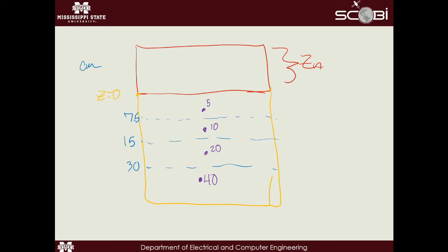And at the very bottom, one of the inputs into the program is something called ZB or ZBottom. And what that does is whatever your input is, you're going to add that to your last soil moisture probe location. So for our default input, that is 30. Sorry, I need to erase this part because this is coming from where this 40 value is. So we're going to say that from here to here, we have 30 centimeters. So the very, very bottommost portion is going to be 40 plus 30, which means that our total soil moisture profile extends down to 70 centimeters.